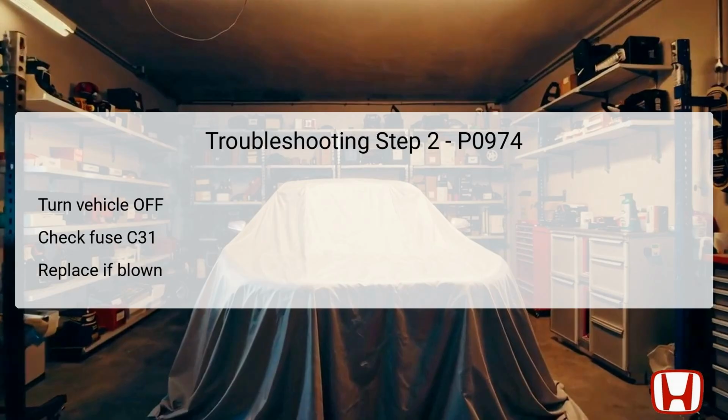If the fuse is blown, replace it with a new 7.5 amp fuse and perform another check. If it blows again, this indicates a short circuit exists, requiring further investigation on that circuit specifically. Fuses serve as vital safety components in protecting electrical circuits from overloads and malfunctions.